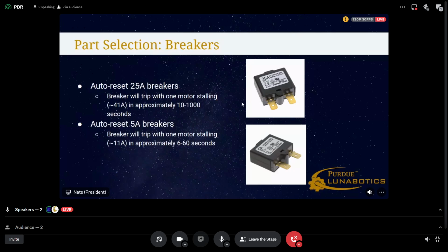It would also be nice, with these new batteries, to know the safe operating voltage, just for software. Yeah, for sure. Off the top of my head, fully charged it'll probably be around 24 volts, and fully discharged it'll be around 18 volts.